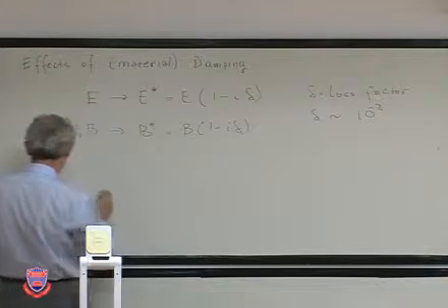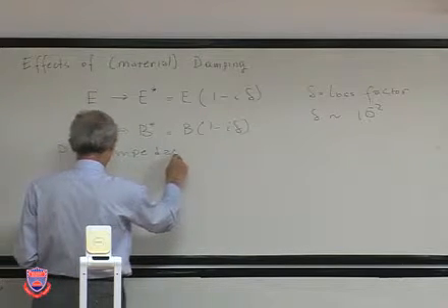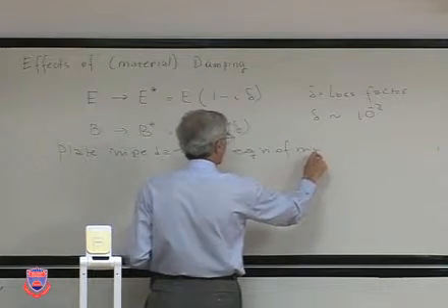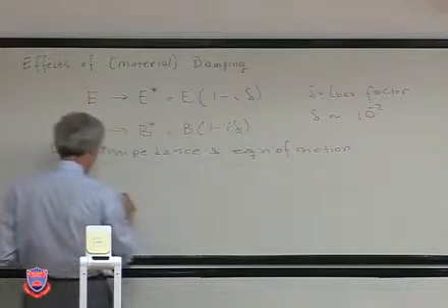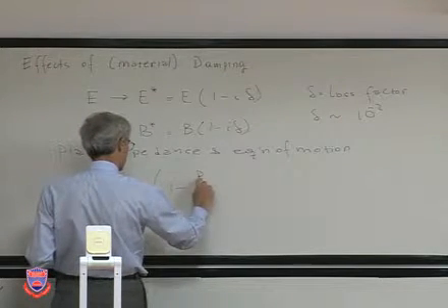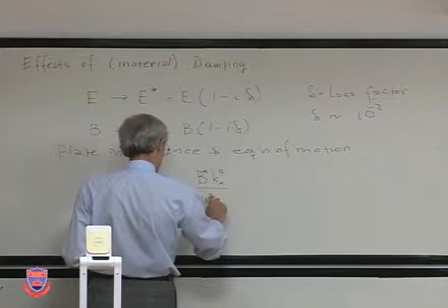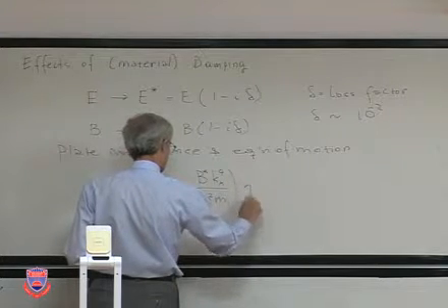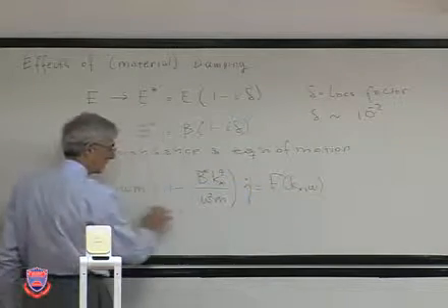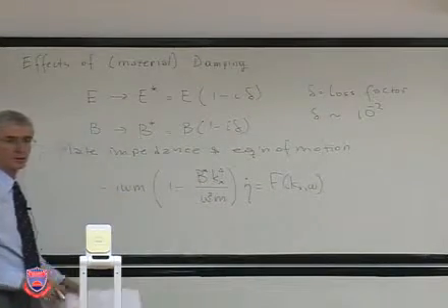And in this case, the plate impedance expression, what we have done is taken the normal plate equation of motion in terms of impedance and made the bending modulus a complex number.